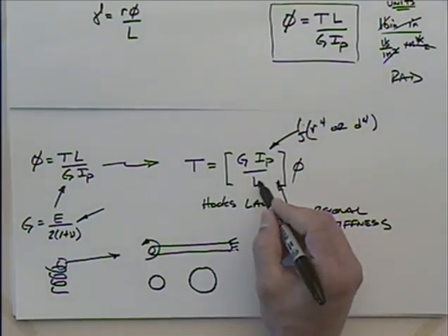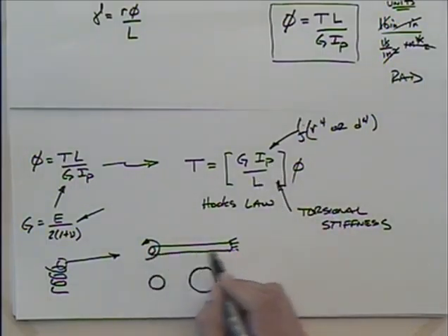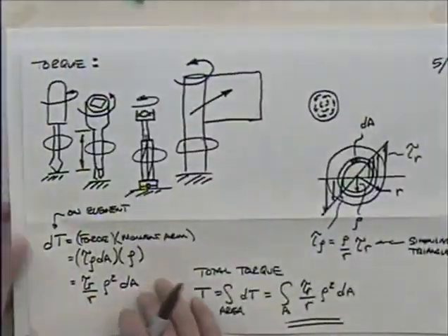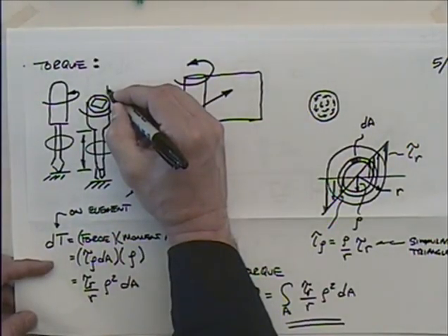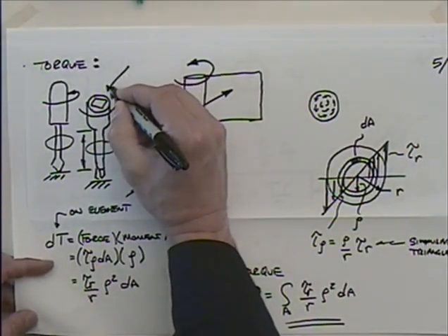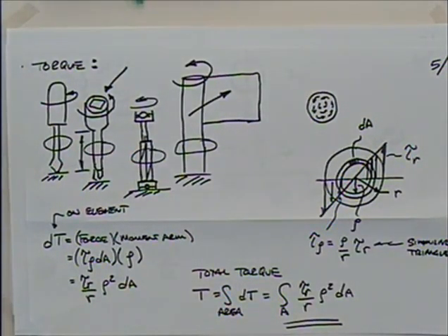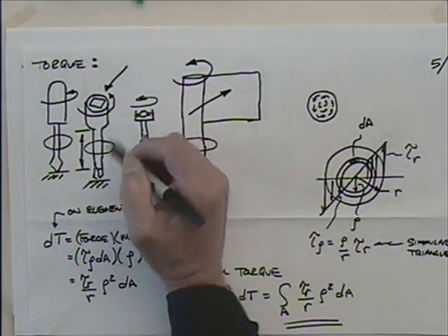And what about the length? If this torsion bar gets longer, what's going to happen to its stiffness? It reduces, right? And that goes back to why we started this conversation talking about this good old extension on our socket set. Has everyone seen a socket set? You've got to get to a bolt way down there, so you get a really long extension and put a socket on the end.